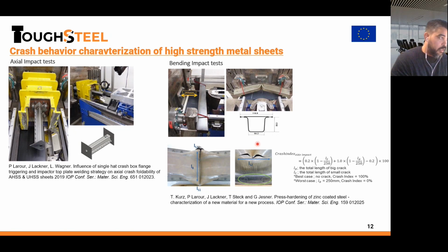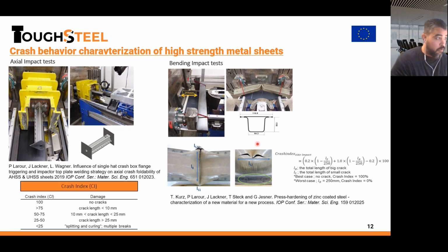In this sense, this is a methodology proposed by voestalpine, which is the definition of a crash index, assigned according to the overall cracking length. You have here the formula to calculate the crash index. You can find a lot of information in the literature about how to evaluate the crash index and the meaning of the different parameters.